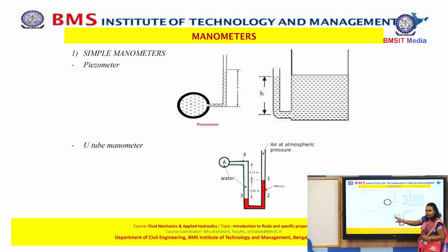then I have the pressure of the fluid in the pipe as PA, and the height of fluid from the datum in the left limb, given as rho g h, is balanced by the pressure of the rise of the fluid on the right limb. So we'll have rho g h, the density of this fluid versus the density of the manometric fluid.